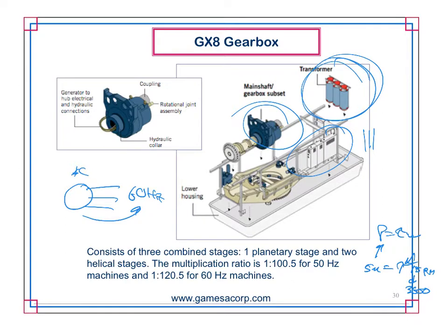The downside is you've got a transformer at potentially 300 feet in the air, so changing that out is going to be more of a task than if you have a transformer at ground level. So getting that up there is not easy. Also, you have to keep in mind that the transformer should be able to come up through the tower in the center and then be set in place.